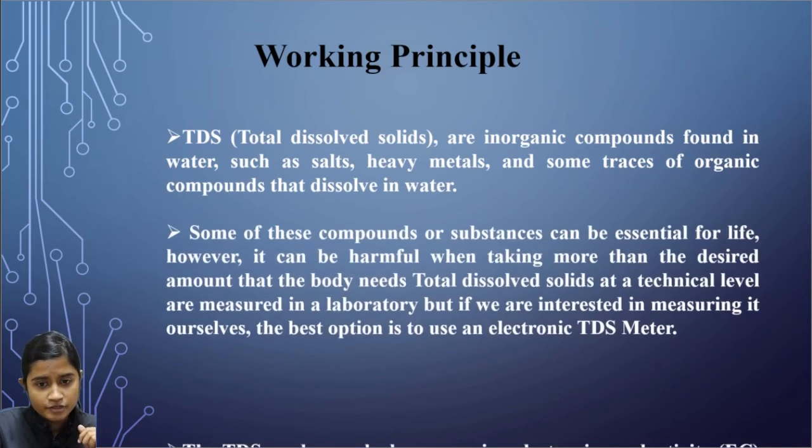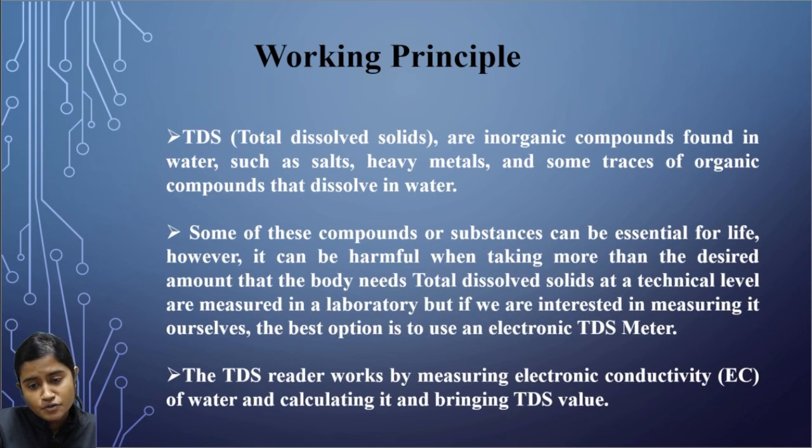Working principle of TDS sensor. If the water contains no soluble materials and is pure, it will not conduct a charge and will therefore have a 0 ppm figure. Conversely, if the water is full of dissolved materials, it will conduct a charge, with the resulting ppm figure being proportional to the number of dissolved solids. This is because all dissolved solids have an electrical charge, which allows conduction of electrical charge between the electrodes.